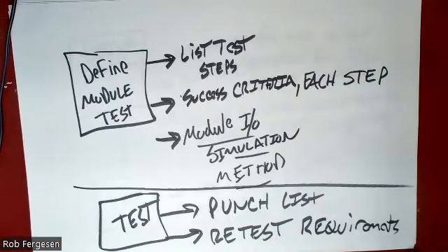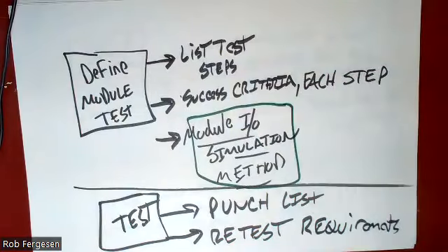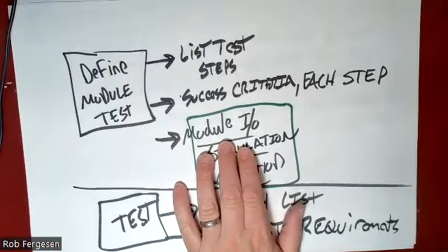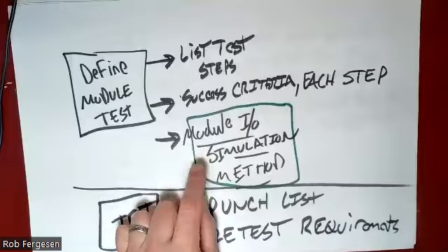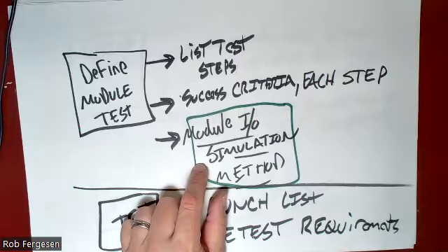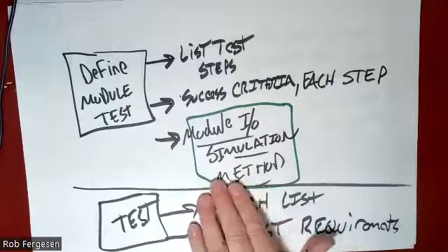So an important step is to create a simulation, so that before I wire up the different modules, before I wire up that robot to a PLC, I have a way of testing to see if my robot program will work successfully. I might not wire it to the PLC right away. I might get a push button and use it as a simulated communication from the PLC to the robot. So I need to come up with a simulation method.